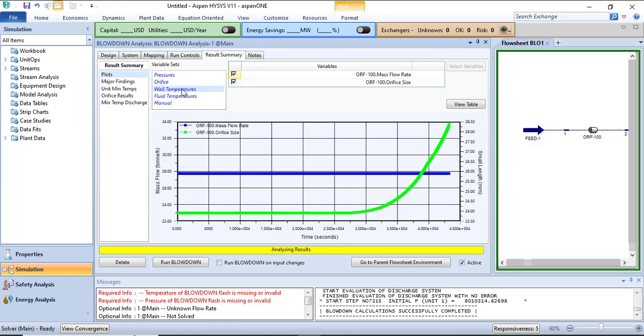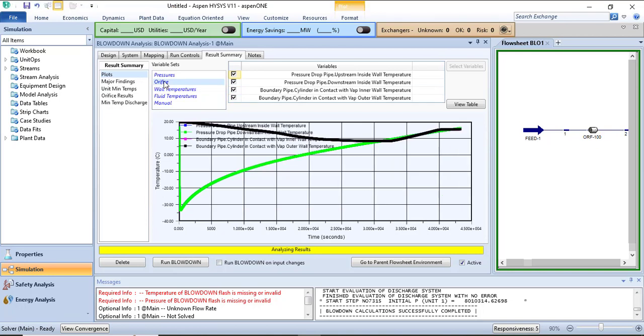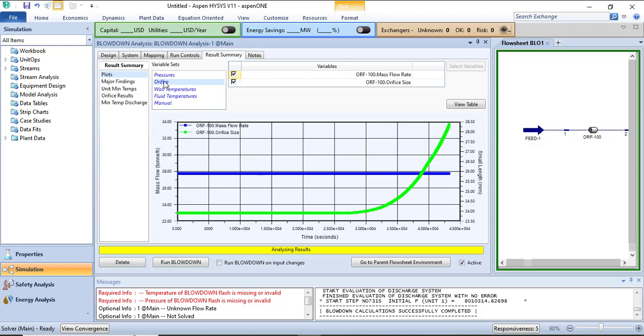One more thing about the orifice: the orifice size will start to increase when the delta P between the upstream and downstream is very low. So the lower the delta P, the higher will be the orifice. So we cannot just focus on this. We have to go until 90 bar to see what the orifice size comes to. We will do one more case for the orifice also.